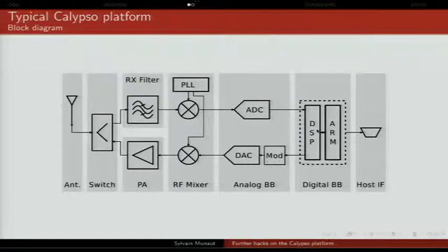If you look at the transmit path, so how the phone actually transmits bursts, it's pretty much the same thing, except in reverse. That is, you send data to the analog baseband, it's up-converted, then it's amplified because you need to transmit with some power to actually get to wherever the antenna is, and it's sent to the antenna. One thing to note, though, is this block. That's a hardware modulation unit.